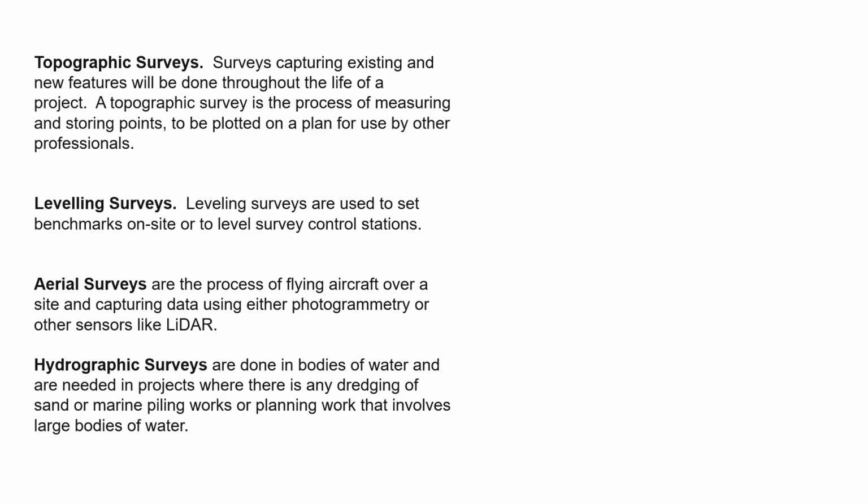Well, for civil engineering surveys, we also need the topographic surface, the ground surface, for groundworks, for example, and leveling surveys are used to set benchmarks on site to level survey control stations. Leveling surveys we use for canalization and drainage systems construction.